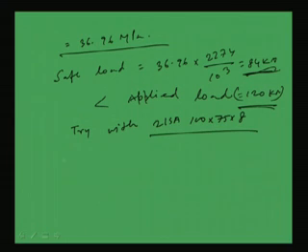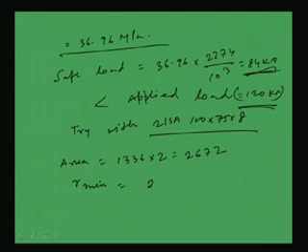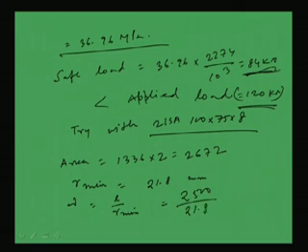Okay. So, now from the structural handbook we can find out the area, that will be 1336 into 2, which will become 2672, and r minimum will be 21.8 millimeter. So, lambda we can find out as L by r minimum, where L is 2500 and r minimum is 21.8. So, this is becoming 114.7, which is less than 350.